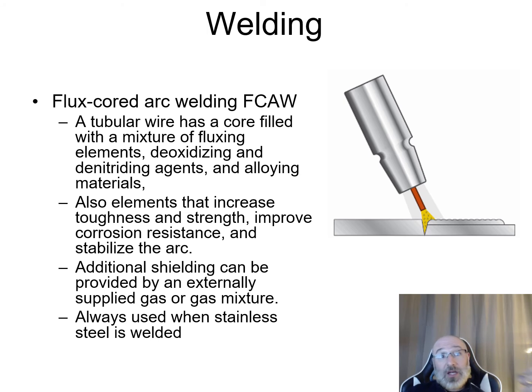Now you can provide an additional shielding agent. This can be used from an externally supplied gas or a gas mixture as well. Typically what this is used for is when you need to weld your stainless steels.